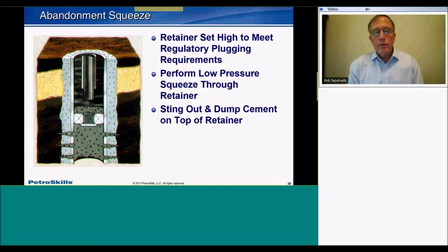Some of these guidelines may be the same among the states. They may vary a little, or they may be a good bit different. But I think one thing that is very close to the same for all the wells is some cement material needs to be pumped into the old production perforations to isolate them, successfully squeeze. So in this case, we have a drillable tool that is set above the top perforations. The tubing has been stung into it. Cement slurry is pumped down below, squeezed into the perforation tunnels.